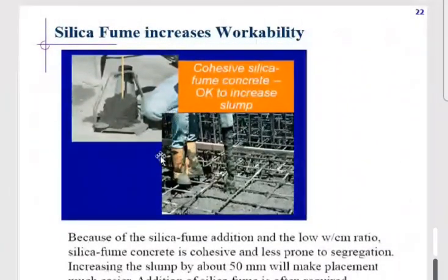Then we have, it is written over here that silica fume increases the workability. However, if you see practically very fine silica fume, you find out that the silica fume actually reduces the slump. But if you see real silica fume, which is being used in the market, where those are round particles at SCM, you may see the increased slump.